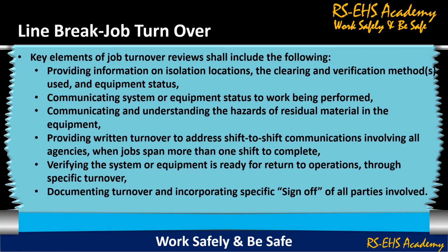Further to the line break step, job turnover. Key elements of job turnover reviews shall include the following: providing information on isolation, location, the clearing and verification methods used and equipment status. Communicating system or equipment status to work being performed. Communicating and understanding the hazards of residual material in the equipment.